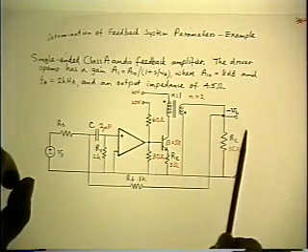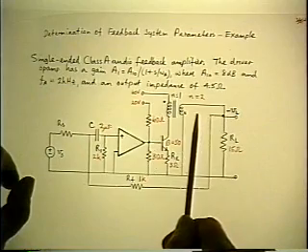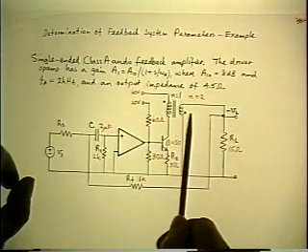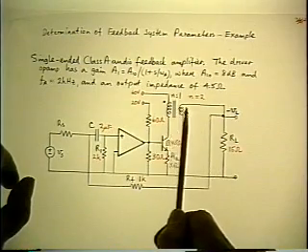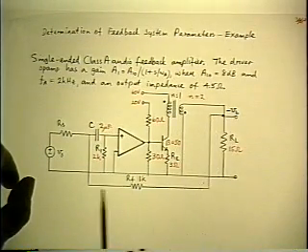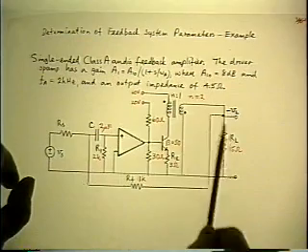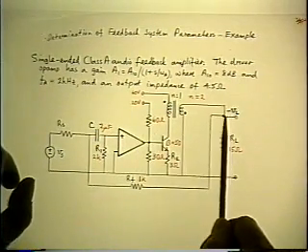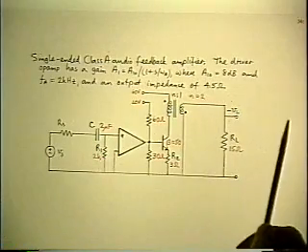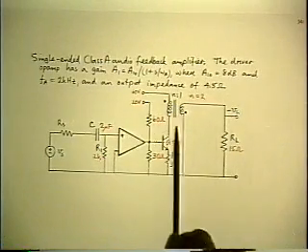Because in the normal configuration, the gain of the output stage is partially affected by a current divider, because not all of the transformer current goes into RL, some of it goes down RF. And that needs to be taken into account in calculating the gain of the output stage. And if you take away the feedback path, that factor is different. So you've changed the A.